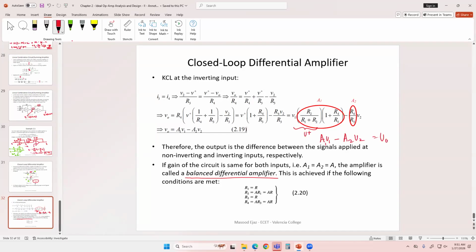So what did we do in this chapter then? We started with, of course, general discussion of operational amplifier. We looked at the circuit, which is a huge circuit, many transistors, resistors, and all those things. We discussed the ideal conditions under which we use operational amplifier, which are input resistance is extremely large, output resistance is extremely low, gain is almost infinity, open loop gain.